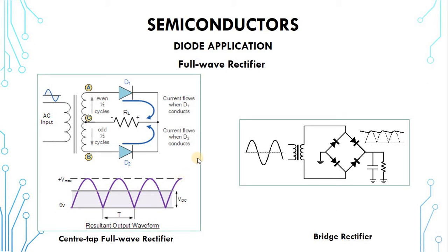So how do we get this to become close to a straight line or a straight line? That is the purpose of the capacitor you are seeing here. The capacitor here is performing what we call smoothing. In other words, it is helping to smooth the waveform, because we need a straight line, but this waveform is just rising, falling, rising, falling, rising, falling. So what happens when you introduce a capacitor in parallel with the load? This is exactly what happens.